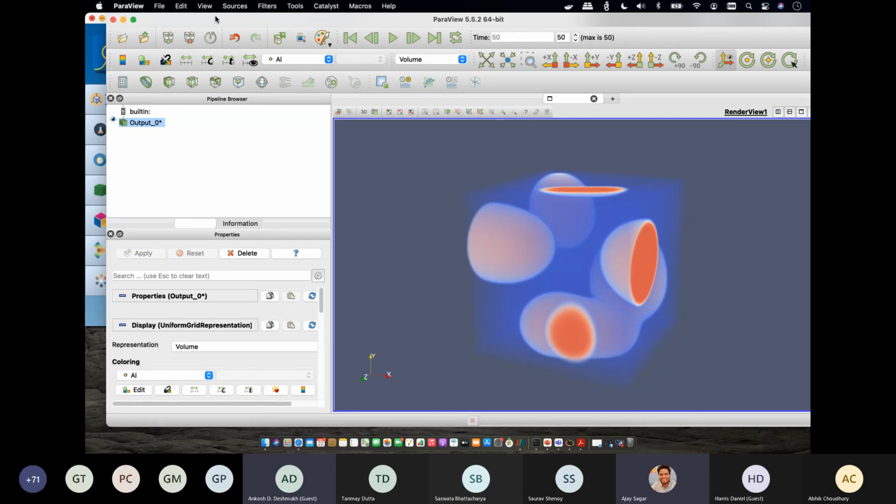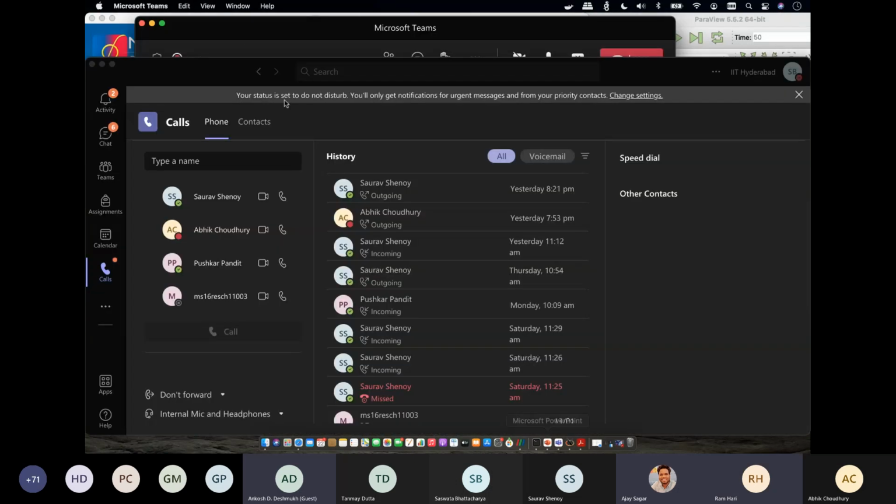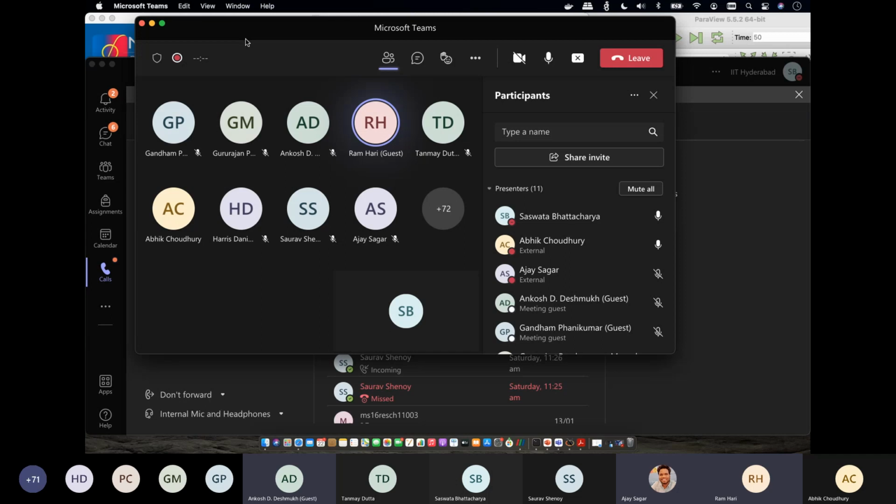Shashta, this is Ram here. Yes. Hey, in these precipitate evolution calculations, these elastic transformation calculations, do martensite-like athermal transformations come in? Yes, we can do that. We don't require to solve the diffusion equation then, and we just have to put in the eigenstrains appropriately. So we can absolutely do that. It's actually pretty easy with this code, athermal transformations.